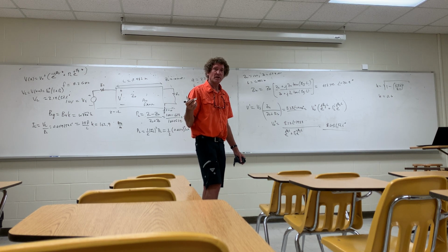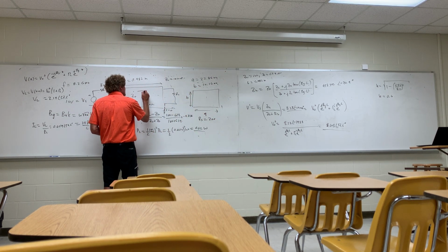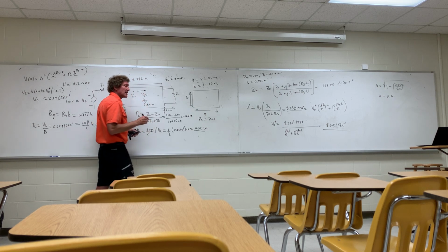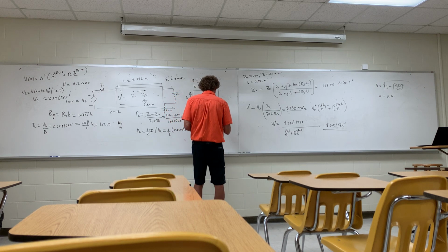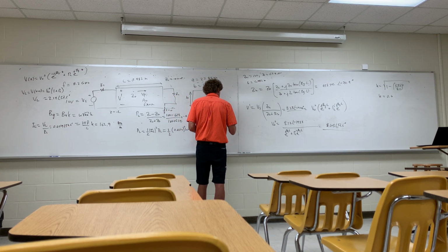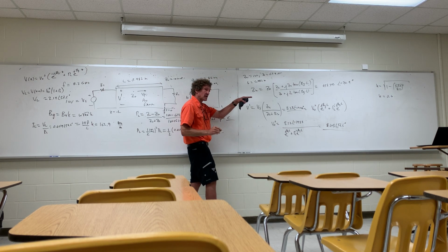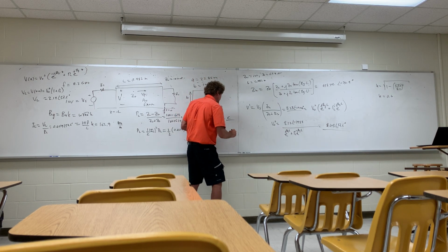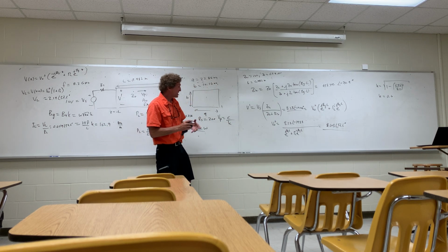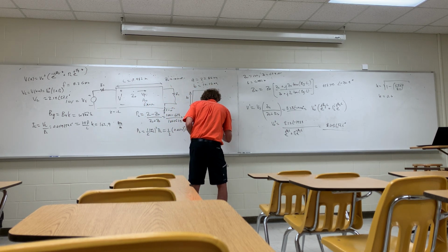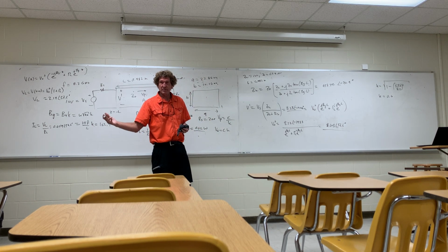That's all. All right, one last thing. If I wanted the velocity in the guide, say the phase velocity in the guide, how do you get it? Phase velocity. Well, it's always the velocity in free space, which would be c, but phase velocity is faster than light, so you divide by k, right? If I want the velocity of energy propagation, what would it be? Or group velocity? C times k. C times k, less than the speed of light, almost, or equal, right?